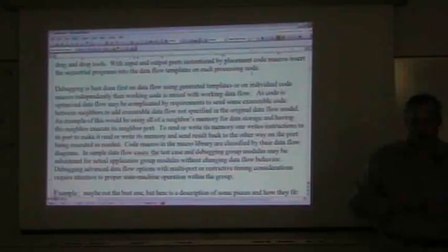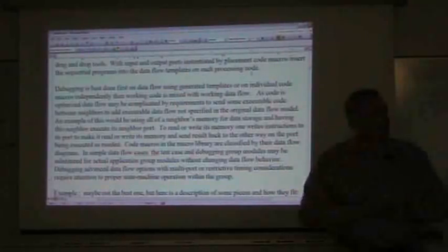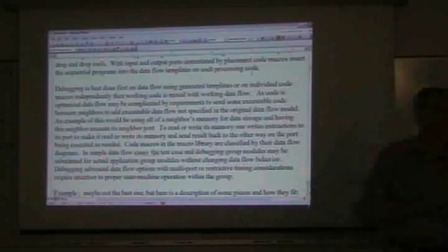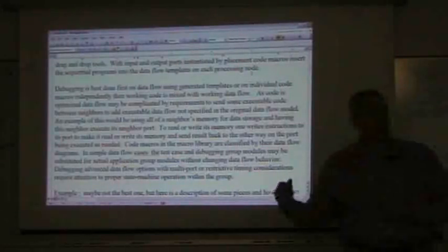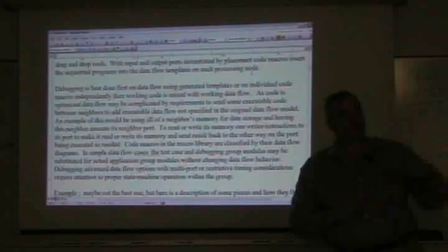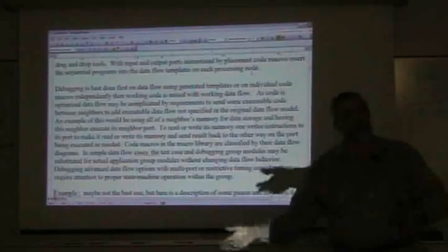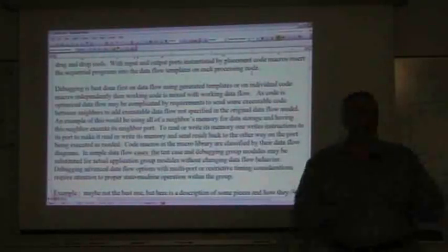Now, I intended to do other things with it, but in the process of debugging this, I thought, well, I've got a number of ways to instrument this. I can send this information over here. I can send it out with pulse width modulation. I can send it out as an analog value. I can send it out as a digital number. Well, I can send it out as a sound on a pin. Why not? It's a trivial thing to do.